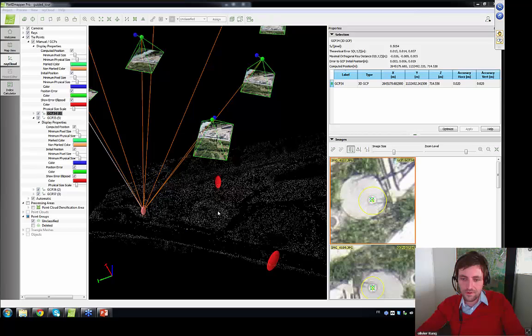So the most important is knowing what type of accuracy you need. You can always go in a project to millimeter accuracy, but to arrive at millimeter accuracy, you will basically have to be very, very close to the object. And the closer you are to the object, the more images you have to take. And then you may end up with millions of images. And that becomes unmanageable, and assessing the accuracy when there are too many images is very complicated.